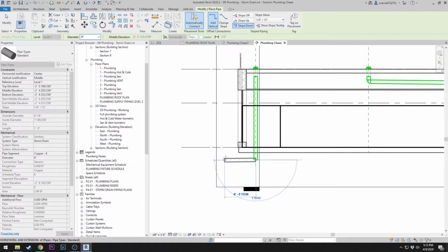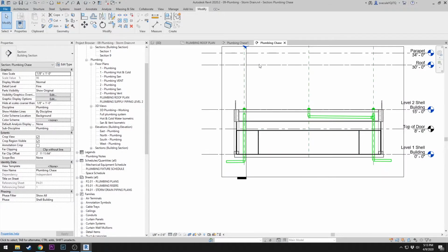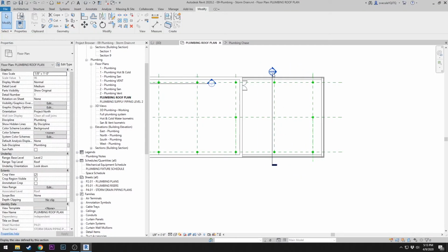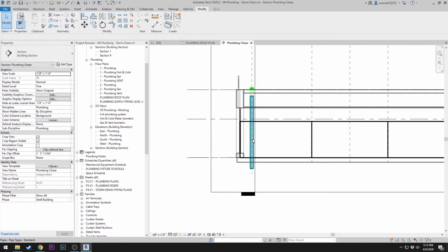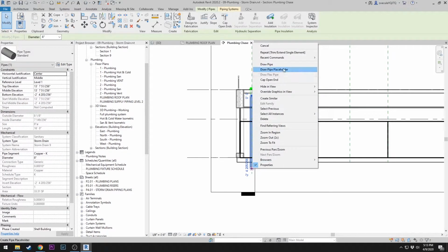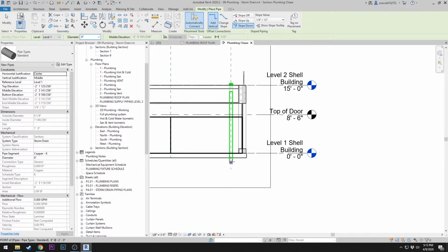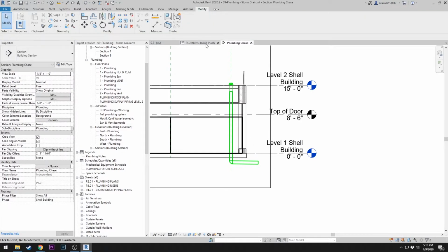Draw a pipe 6 foot. And then we just work our way down, doing that to each riser pipe. I'm just starting the pipe and then pulling it out in the direction, typing my measurement. So 6, enter, and it pulls it out 6 feet.